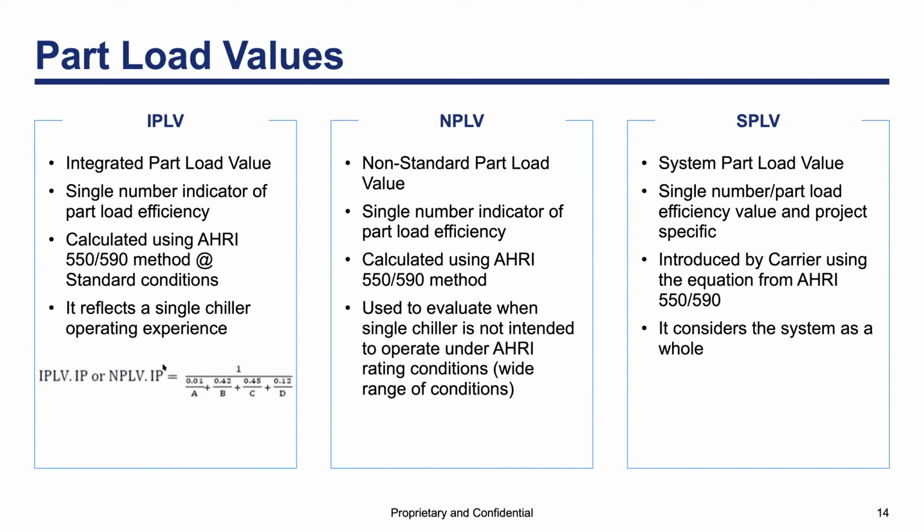Right in the middle, the NPLV, once again Non-standard Part Load Value, is calculated based on conditions relevant to the site. But like the IPLV, it is for a standalone or single chiller. Notice that the IPLV section includes an equation which is valid for both IPLV and NPLV. We're going to talk more about this, especially the numbers in the denominators as well as the letters, in the next slide.